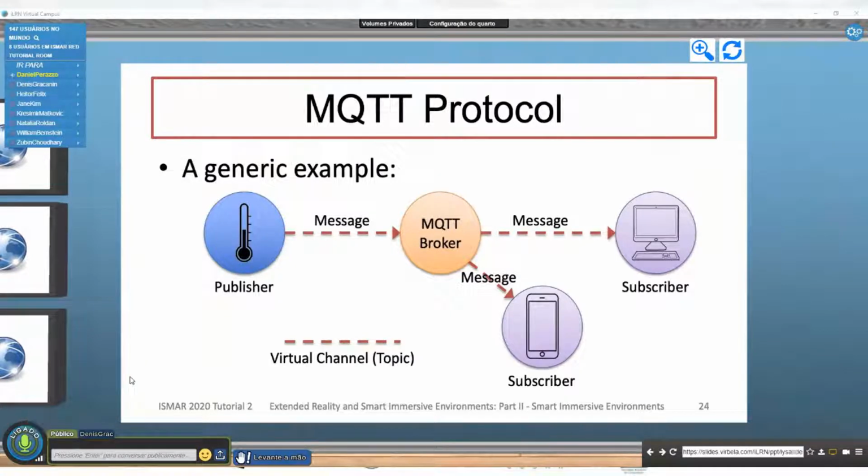When we want to publish some data, the data is associated with topics, so we can have a number of topics, and therefore different publishers for different topics. A subscriber can subscribe to several topics. Again, it is the role of the MQTT broker to efficiently connect the publisher and subscriber.